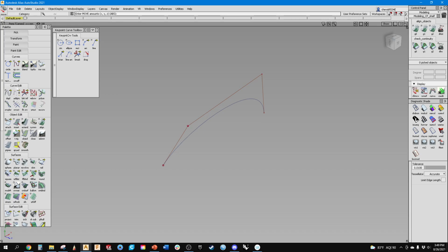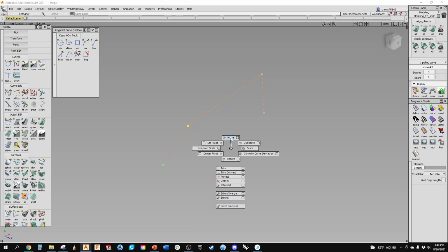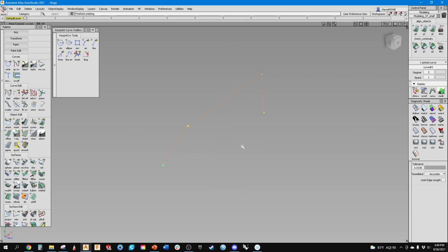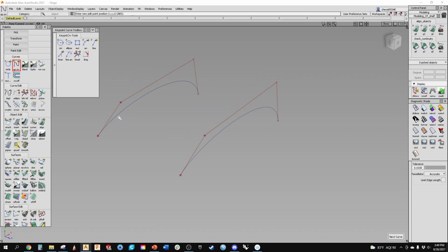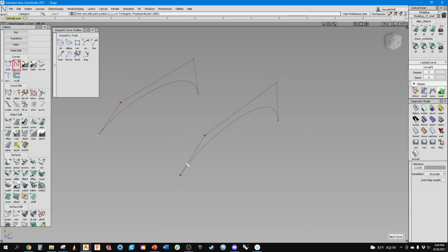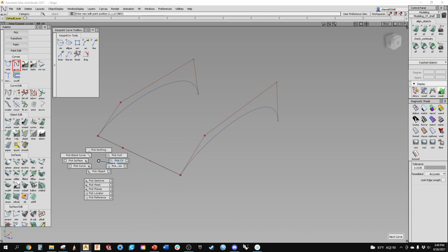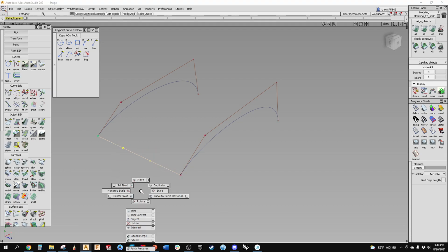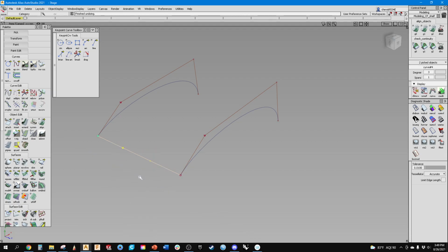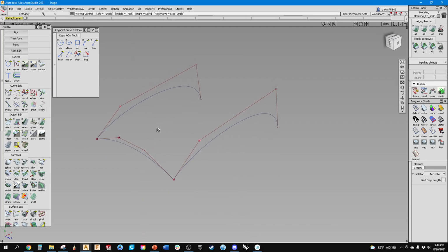So what I can very easily do is pick this surface or this sketch. You can see V. I'll move it over to here. What I'll do is another sketch here. And I'm controlling these all by these CV points to get that shape.